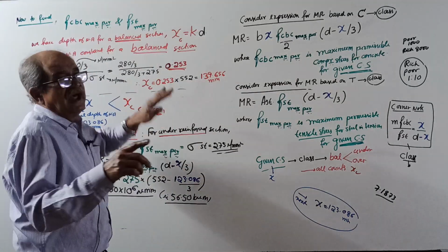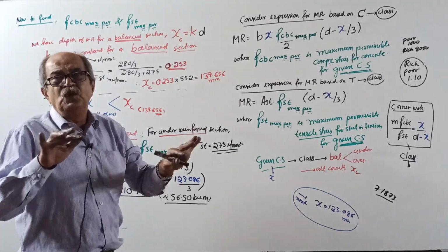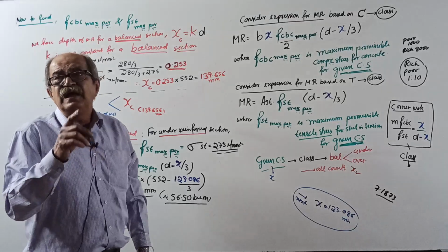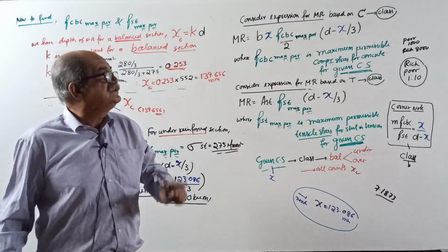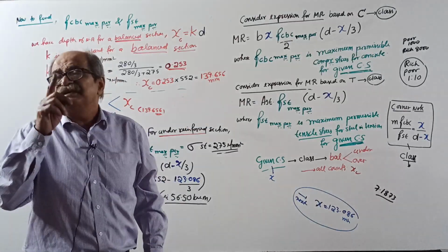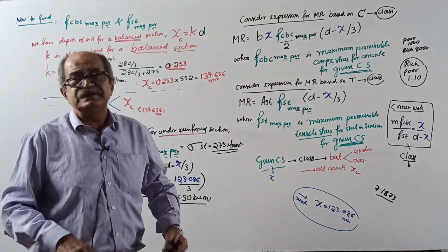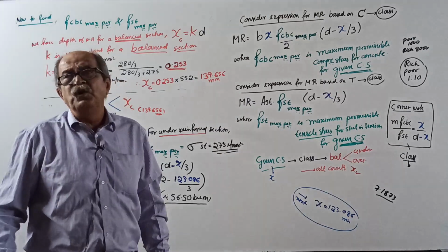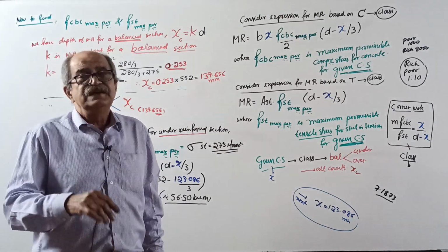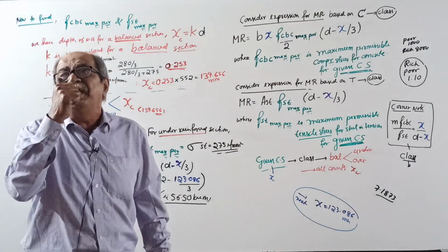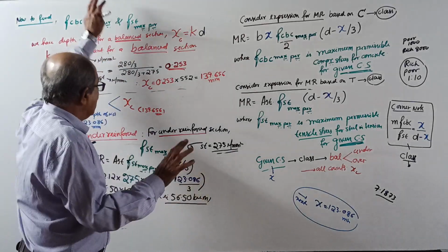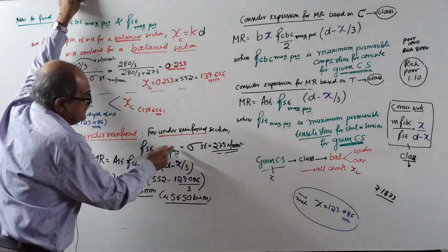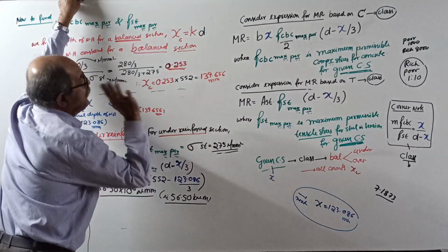For an under reinforced section, remember one thing: whichever is weaker, steel weaker, critical stress, the maximum limit will be reached on the weaker side. In structural engineering, remember, strength always depends on the weaker, not the stronger. So in an under reinforced section, steel is critical, and the stress in steel will reach the critical 275.